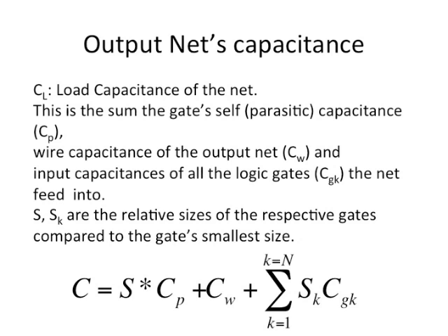And then the input of every logic gate this connects to will have its own capacitance, which is basically the gate capacitance of the transistors. You have to sum up all the gate capacitance of all the transistors of all the gates to which this net is connected. So that is the gate capacitance.